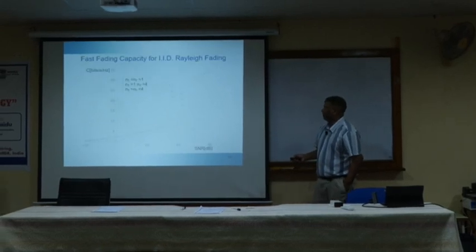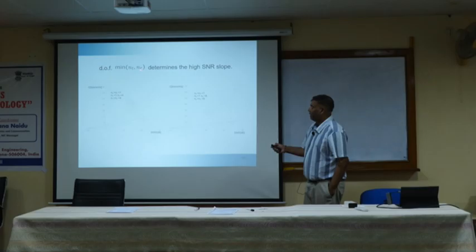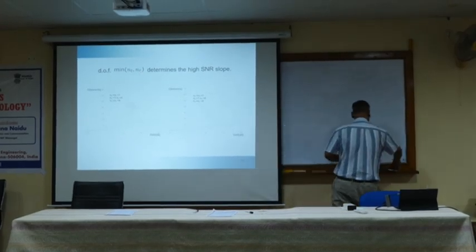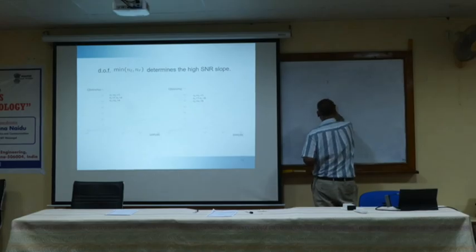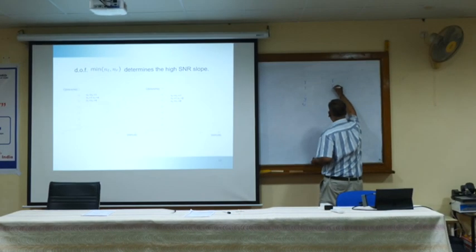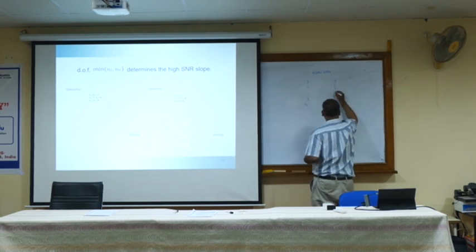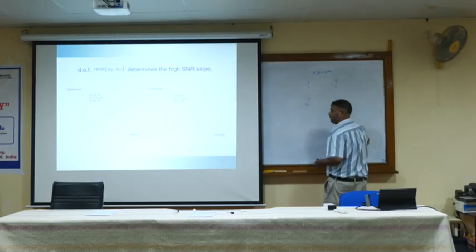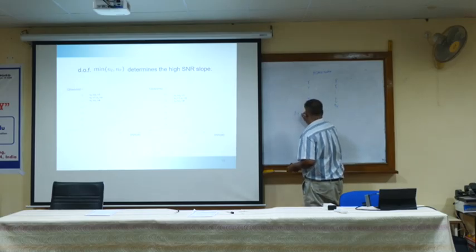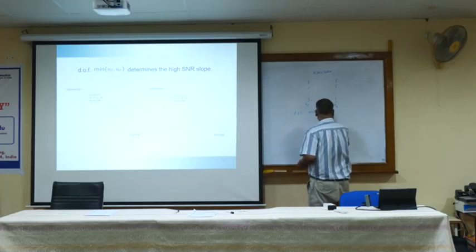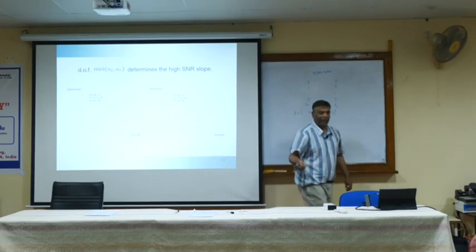Gains. So yeah, the MIMO system will give you a minimum of NT comma NR. So if you have NT transmit antennas and NR receive antennas, there is a performance degree of freedom gain that is min(NT, NR). Okay, so this is the degree of freedom gain or spatial multiplexing gain.